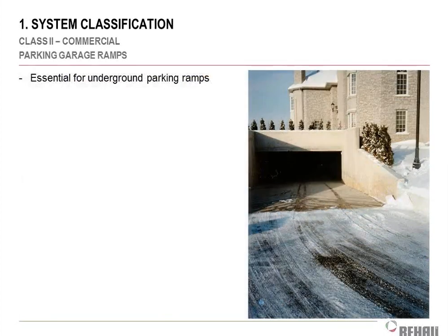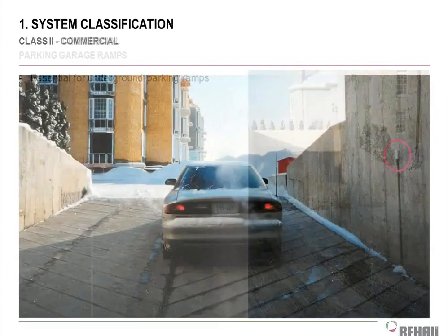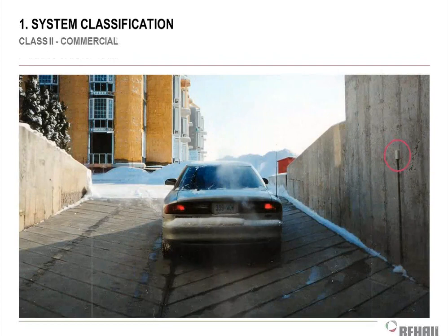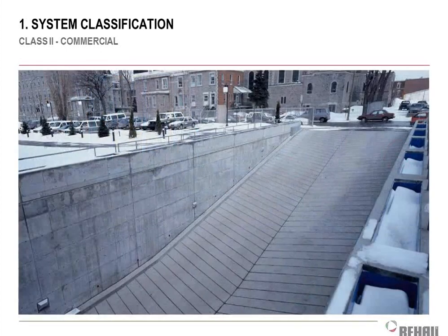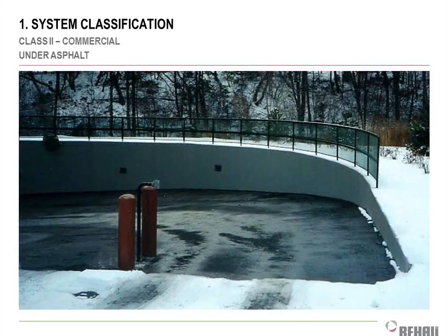Parking garage ramps are actually a huge application. We do quite a few of these because it is difficult to drive your car up an icy ramp and get out of your parking garage without sliding backwards into someone else's car. So we do quite a few of these kinds of applications, and it doesn't really take that much energy because you're not doing a whole parking garage. You're just doing this one ramp. So we do that quite frequently. And you can see over there on the right-hand side there is a sensor on the wall to turn the system on, and we'll talk about controls here in a minute. So parking garage ramps are a big application.